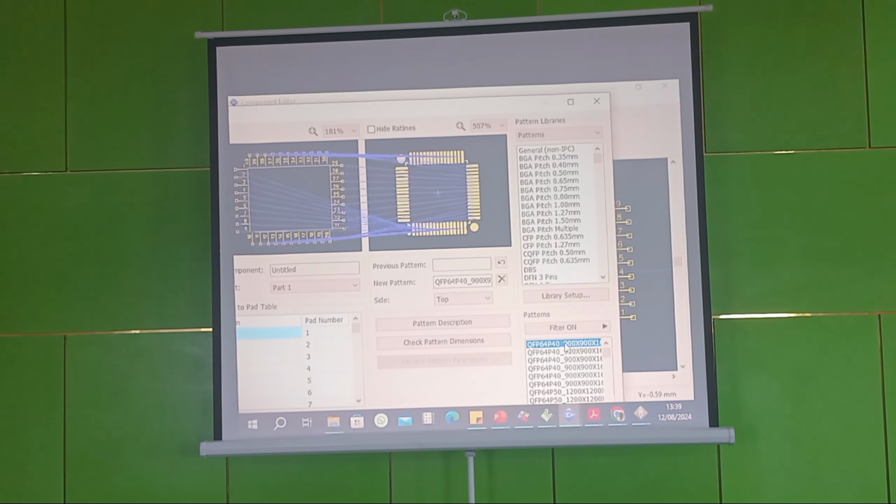You understand now? So this is a standard. Nobody can change it. The only thing the manufacturer can do is to tell you their pin function may be different. I can say my own pin number 3 is voltage, 5 is ground. But that component must sit properly on this pattern. So all what you are just doing is just for you to know how you can also do it yourself. So there's no component now.